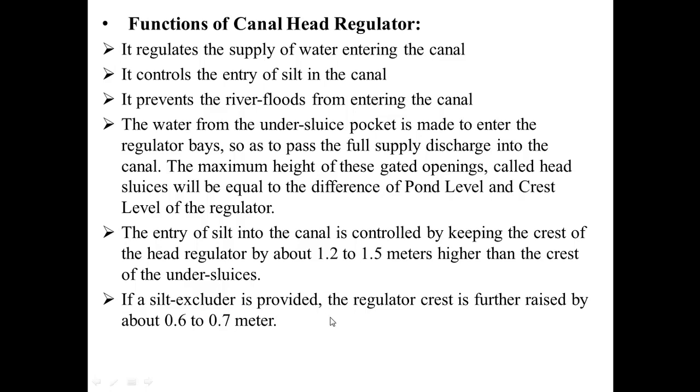If a silt excluder is provided, the regulator crest is further raised by about 0.6 to 0.7 meter.